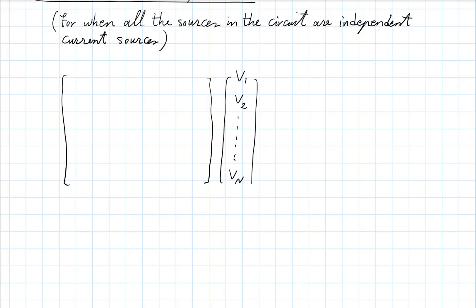If you go back to the examples we did yesterday and before on nodal analysis, you saw that on the diagonal, you would end up with the sum of the inverse of the resistances that are connected to that node. Okay? So let me write this down, and you'll see. By the way, G is sometimes used for conductance, and conductance is just inverse of resistance. Okay? So your equation will look like this.